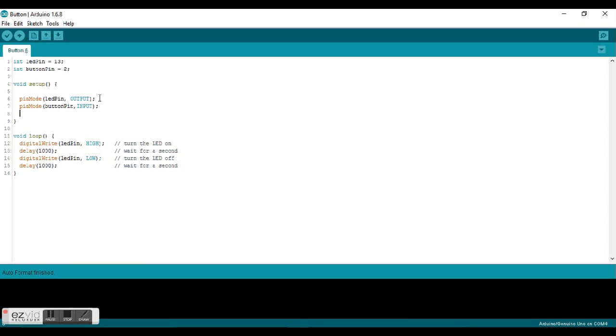Second thing I want to do is actually utilize our serial monitor. And so our serial monitor allows us to see what is going on between the Arduino and the computer. So it sets up a communication. So we're going to use a library called serial. And we have to use serial.begin. And we're going to tell it we're communicating on 9600 baud rate. So this opens up a channel between the computer and the Arduino. And for now I'm going to just delete what we had in void loop. And we're going to go ahead and send our button information back to our serial monitor.